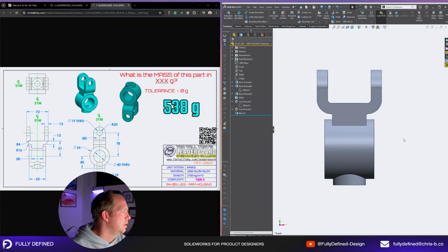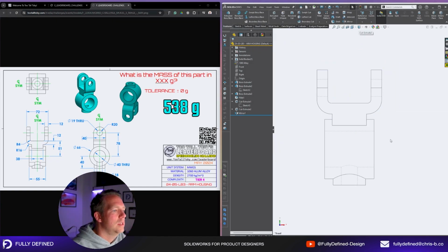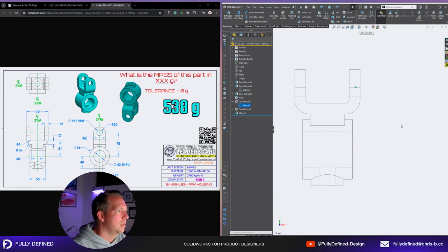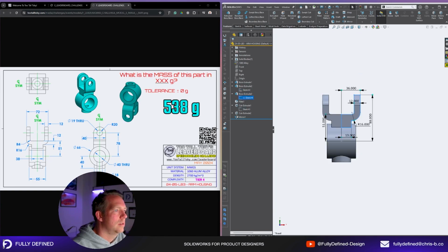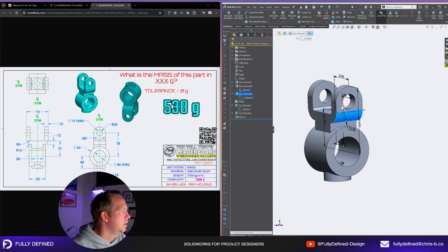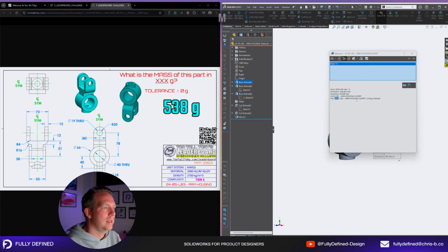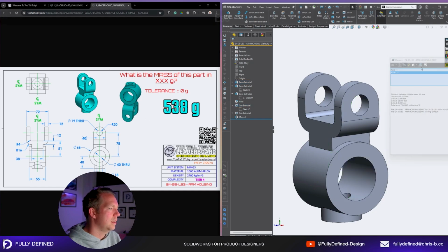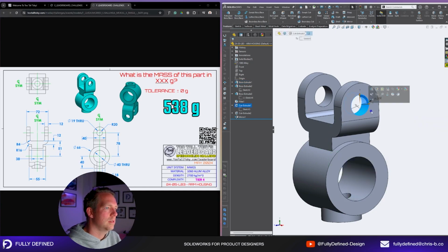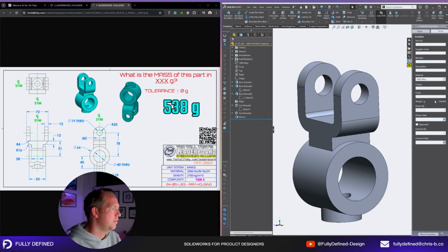Alright, so again, just assessment mode. I have a look at those hidden lines. They look pretty good. We've got lines going through all. Have I got anything wrong with the height? That was a little bit annoying, that dimension there. Should be 40, 20, 19. So from center to center should be 78, 68. Radius of 20. Yeah, that was my mistake. So that should be 98. It looks better. And 538, there we go.